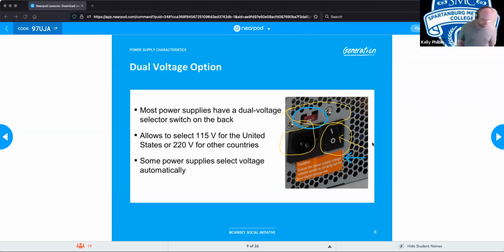Yes, Humberto. Will you please show which are the rails? I didn't understand that. The rails are just about the amount of wattage or voltage that's coming out of the power supply itself, because each rail can only handle 12 volts. Older power supplies, everything in that computer could be supplied with enough power under 12 volts. Computers nowadays require a lot more power than that. So you have what they call a multi-rail system, where they have several, like 4, 5, 6, 12-volt rails running through there. It all depends on the power requirements that you need to run the components in your system.